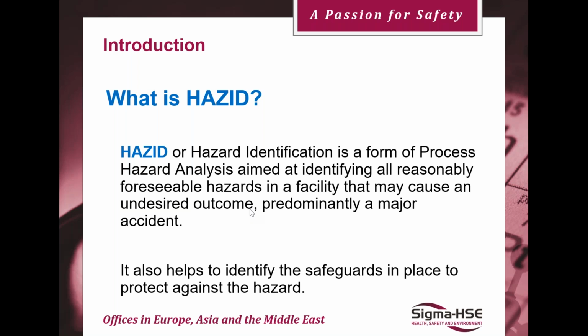So these are to do with fires, explosions, the release of toxic material where you have a large number of people or multiples of people whom you can hurt. So we identify what those are, and in doing that, we're not so much looking at the slips, trips and falls aspect of safety, the so-called occupational safety. We're looking at the process safety features. And you can think of those simply in terms of a loss of containment of a hazardous substance, one that has the potential to cause harm, where that harm can be realized in the form of a toxic release, hurting people, fires and explosions.